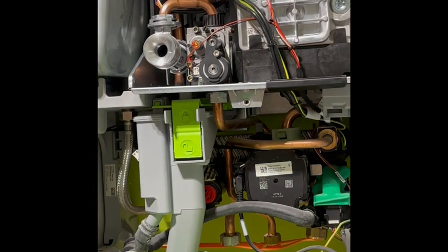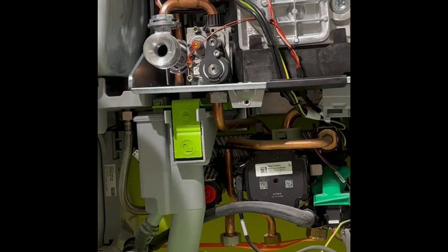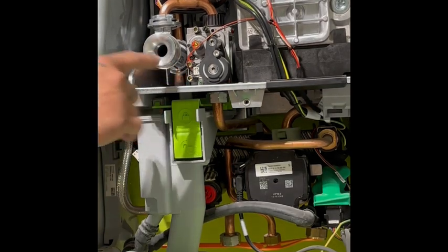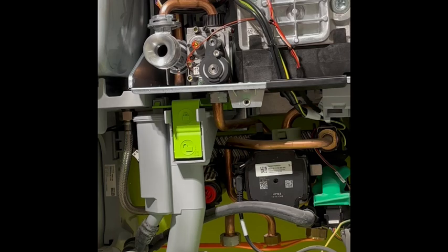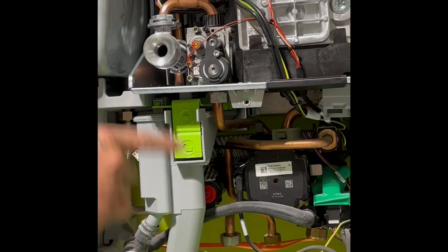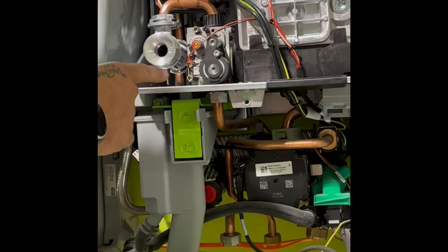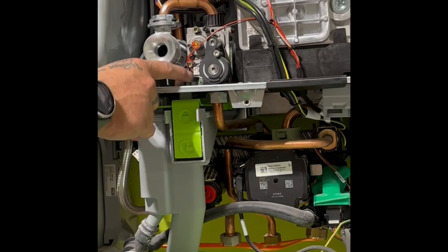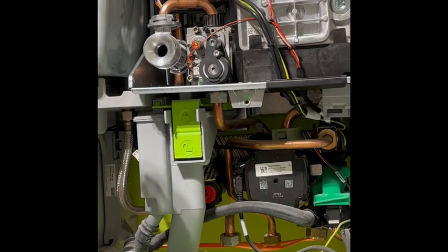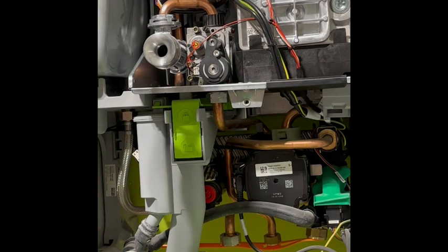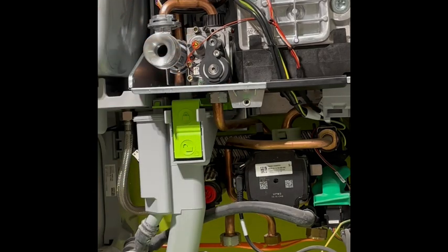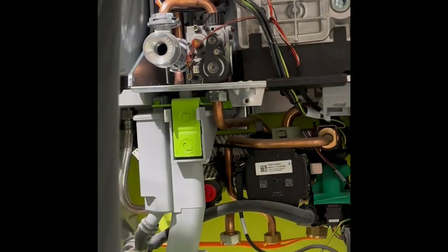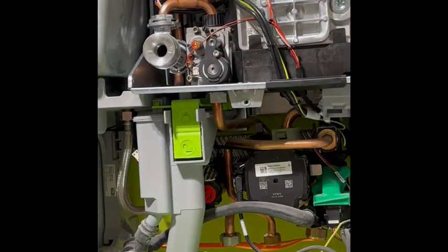Does it light? Does it go out after a certain time? Is there a time of day that it's playing up on? And we're going to be measuring, just remember this, that your gas ignition fault starts from the service in the ground. So there could be a fault anywhere along that line, up to the gas meter, all the way to the boiler, that's going to cause that fault. So first and foremost, you want to be putting your gauge on P1 of the gas valve and running it through its ignition sequence. And then just seeing if there's any movement at all in that gauge. So you will see, let me just grab it.